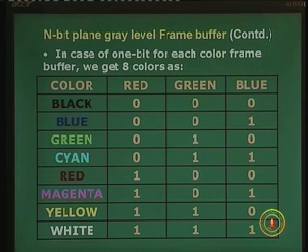The first row talks about red, green and blue, all 3 zeros, and we have the black color, which is of course very obvious because none of the electron guns are firing with an intensity. The beam is switched off and the pixels also do not glow. So, we have black, and at the bottom of the row, when all of them burn simultaneously and hit the corresponding 3 pixels, you have the white color. Okay? And in between you have other variations, of course, the pure blue and the green and the red